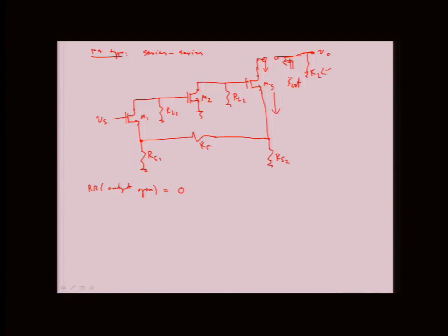So it's series at the input because that current involves voltage across RF, and that's going to change the source voltage? Well, yeah. So that will be your feedback, and then this is sort of your V error, right? So I feel like I could also make that look like a shunt in my head with current going through that middle branch. You can't, because that would mean that the current has to come from the input. And then your signal processing is the input current minus the feedback current, right? That gives you the error. But here you don't have the input, right?